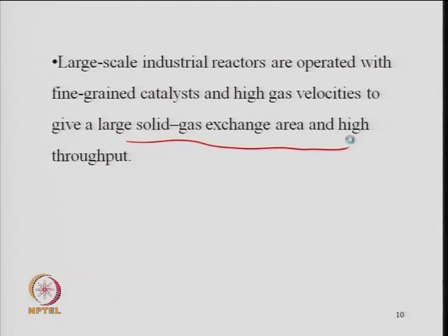and then we have to include those terms in the reactor design when you look at the average conversion, because in the fluidized bed it is not a conversion at a particular point, it varies down the length, and there is a kind of back mixing also. So, you have to introduce the residence time distribution, and then calculate the average overall conversion in a reactor or conversion down the length or concentration profile.